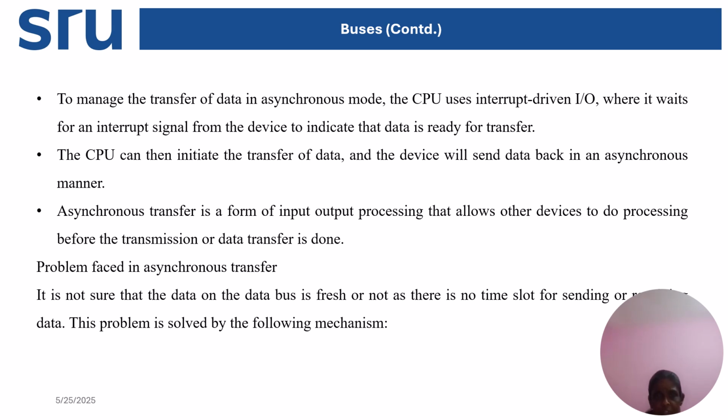To manage transfer of data in asynchronous mode, definitely an external force has to be applied, because in the case of synchronous, the clock is enough to manage everything. The CPU uses interrupt driven I/O. So instead of a clock as in synchronous mode, we are using interrupt driven I/O in asynchronous mode, where the CPU waits for an interrupt signal from the device to indicate the data is ready for transfer.